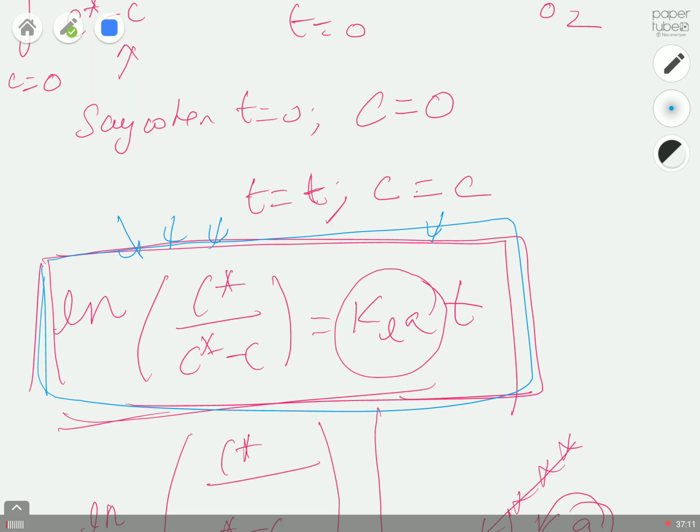So you supply gas, the oxygen bubbles enter the reactor, and you have to push the molecules from the bubble to the liquid, and that happens naturally because you have a concentration gradient. But as I said, you can dissolve only 7.7 milligrams per liter, which means the concentration gradient is also not a big number.